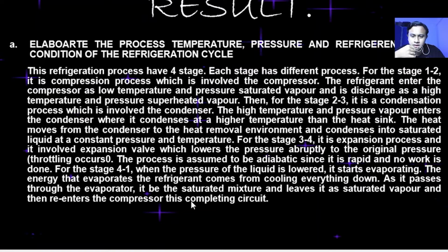and temperature. For stage 3 to 4, it is the expansion process and it involves the expansion valve which lowers the pressure abruptly to the original pressure. There is a throttling process that occurs. The process is assumed to be adiabatic since it repeats and no work is done.